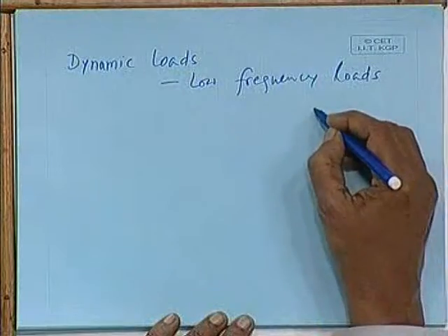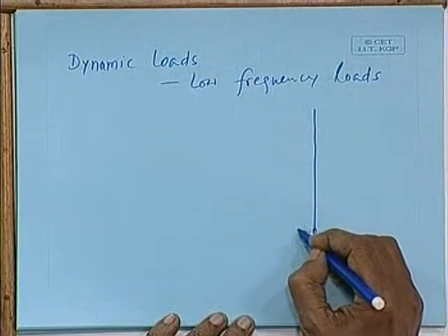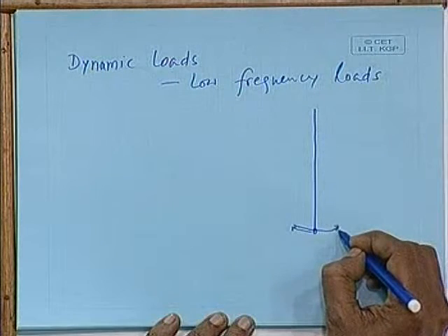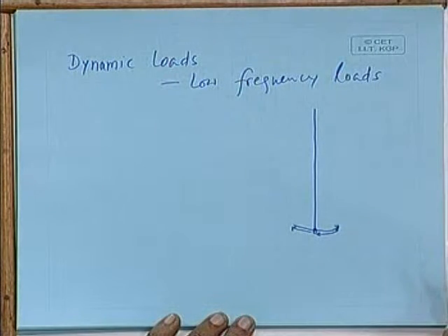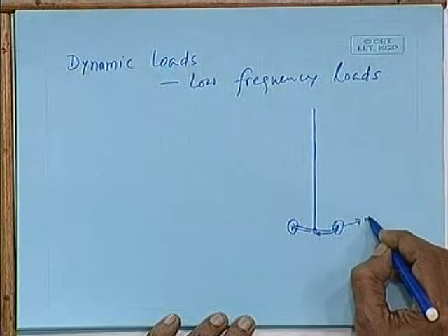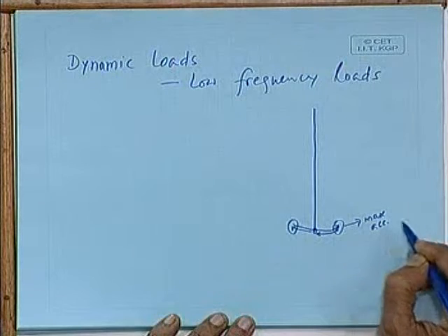When the ship oscillates, you can understand that in any oscillatory motion, take any simple harmonic motion, acceleration keeps changing. And where is the acceleration maximum? At the end of the rotation. If I have a simple harmonic motion of a simple pendulum which goes this way, then comes back this way and comes back here, then the acceleration is maximum here at the ends, isn't it?